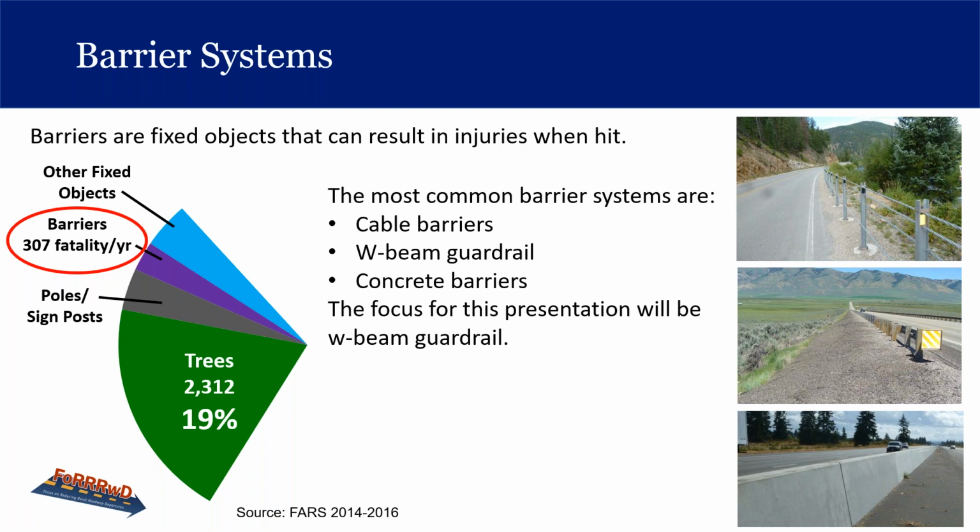And so barriers are often a last resort. We're going to look at parts of barriers, requirements for use and testing, and common problems with installations or in-service barriers and maintenance concerns. If objects or harmful effects cannot otherwise be mitigated by removal, relocating, or being made crash-worthy, then a barrier may be the last resort. Barriers will sometimes increase crashes, but the increase is usually the minor variety or incidental contacts.